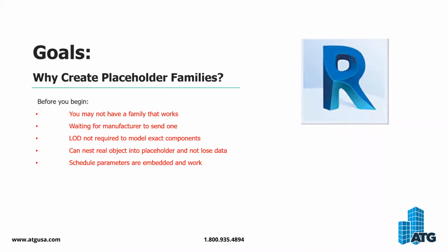And if ceilings were all different across the entire model, then maybe there's 20 different ceiling heights. That means I would have to have 20 different work planes just to attach those correctly. So little ideas like that mean an unhosted family would work a lot better. In that case, I would just change the elevation in every room and be able to do any connections if I had conduits or pipe fittings or sprinkler heads or air terminals, things like that. Any of those could be theoretically unhosted objects if I used a placeholder family to build them.